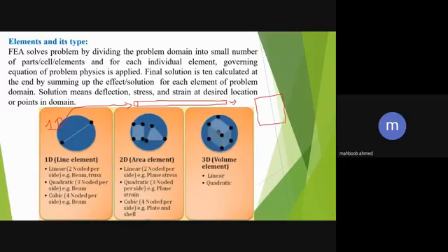In plane you have large dimensions, but in thickness it is very thin, so you can ignore the thickness, and in those cases you use a 2-dimensional element. Now the third, the 3-dimensional element: these elements have length, width, and thickness also.